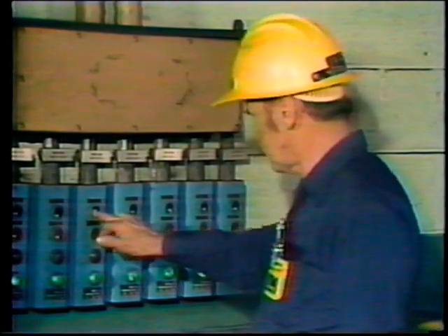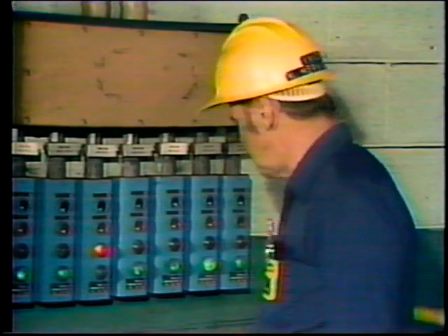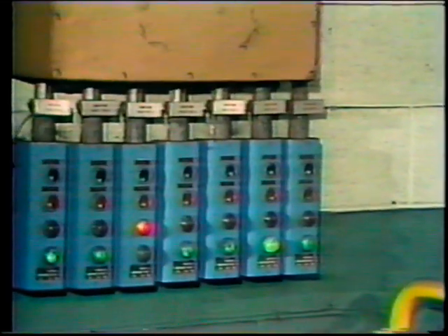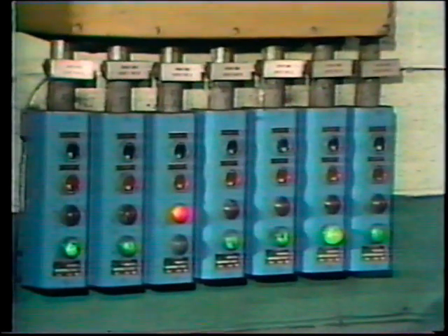The controller should now operate normally, so the controller's tag is removed and the controller is energized. But before the controller can be returned to service, it must be tested to make sure that it is indeed operating normally. The operator starts the motor and allows it to run. The electrician monitors its operation. It operates normally, and the turbine fan it runs can be returned to service.